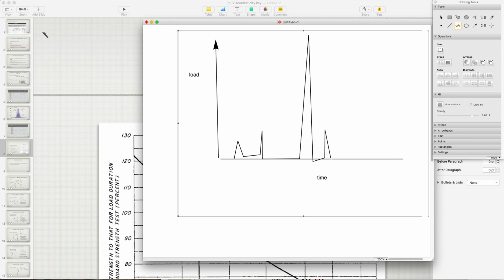It's not constant over time. But what they've rationalized is that if you go over the life of a structure, which is assumed to be 100 years, and you add up all of these events and add them together, they'll add up to be 10 years over the life of a structure. So 10% of the time, there's actually somebody in the room.